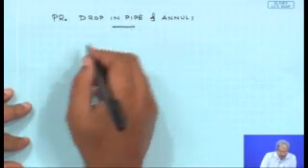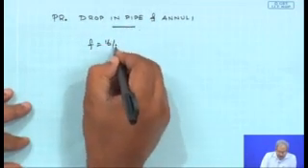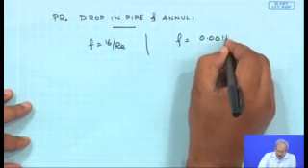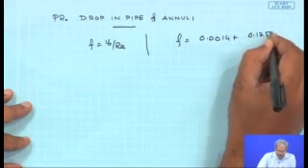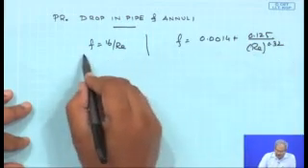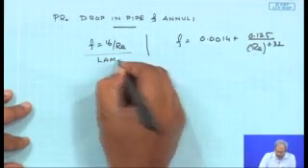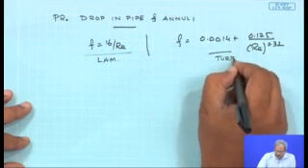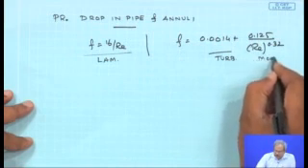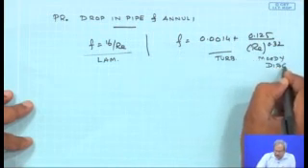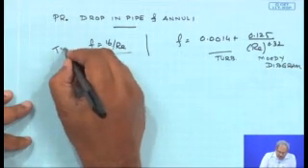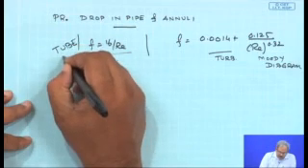if it is laminar, f equals 16 by Re; if it is turbulent, it is 0.014 plus. All these relations are known to you. So, this is for the case of laminar flow, this is for the case of turbulent flow. You can use either this correlation or you can simply use the Moody diagram. Okay. And this is for the tube or pipe.